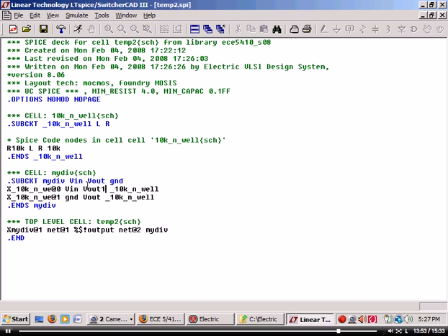Okay? But it doesn't care. Let's see, where's the node? Here we see the node name. In some SPICE simulators, you can input this netlist, but when it goes to try to simulate, it won't know. This will confuse it. So like if you do an op amp and you use V plus using the plus symbol, it doesn't work in some simulators. And so it's best to avoid funny names. Just avoid pain. Any questions? Yeah.